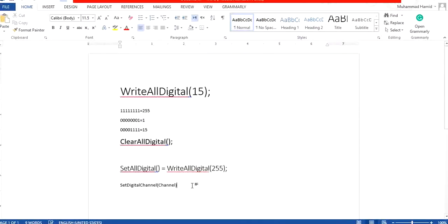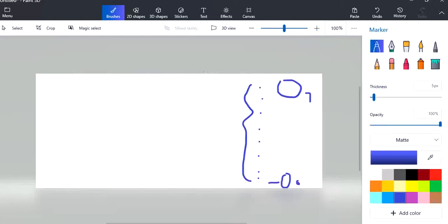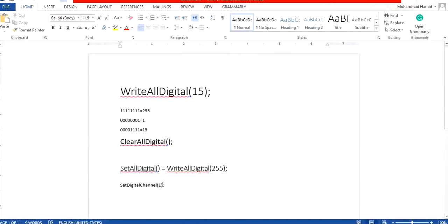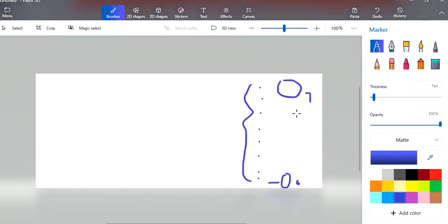So we will write here set digital channel, and let's say I write set digital channel 1. What will happen? The first output, O0, will be on. We can say O1. And when I write set digital channel 8, then this one will be on, O7 will be on. So you can say in this case it is O8.